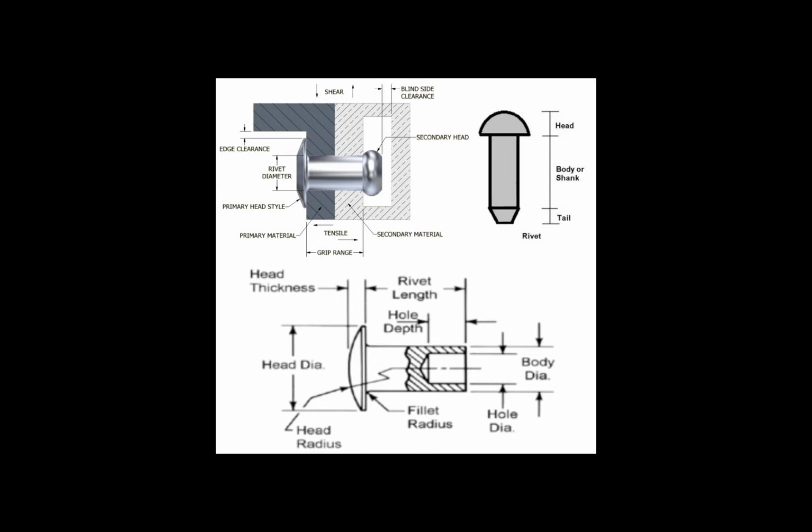Backed with wood, feed slowed, drill bit modified to a 60-degree tip angle. What do you do to a drill bit before drilling through plexiglass? Modify to a 60-degree tip angle.